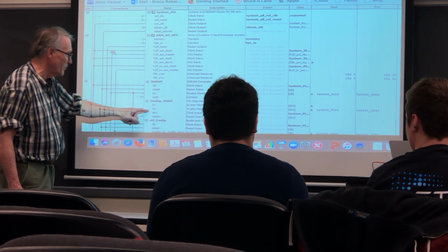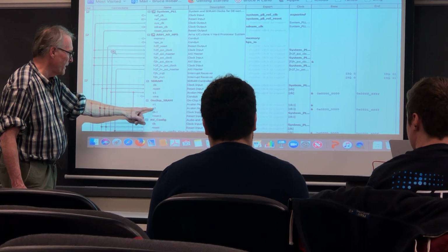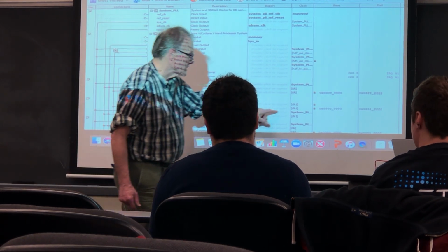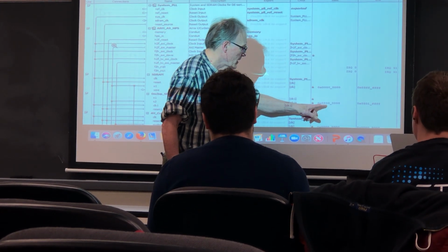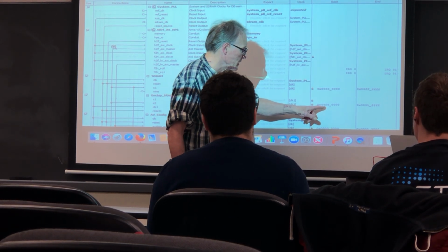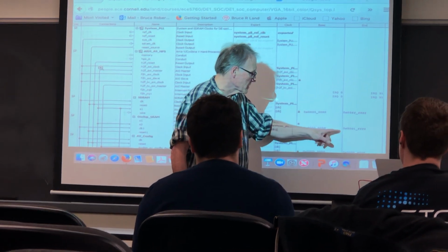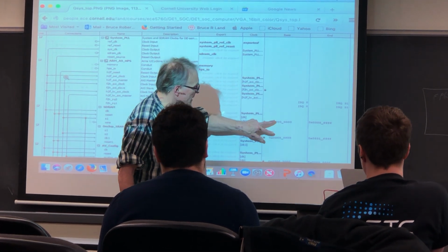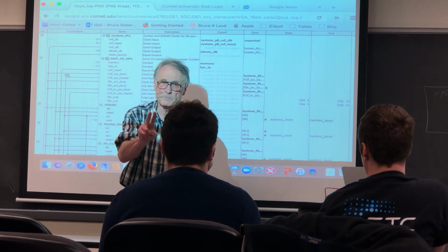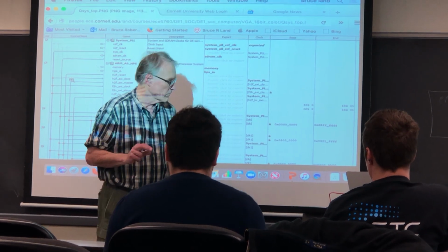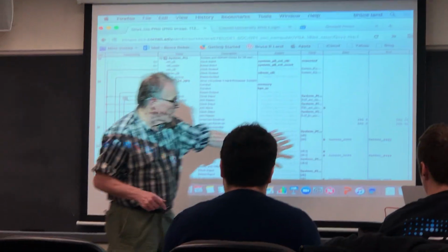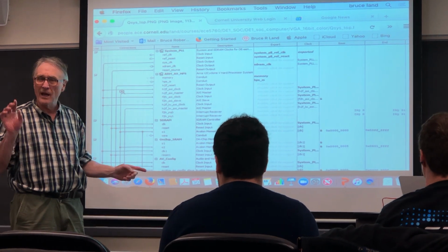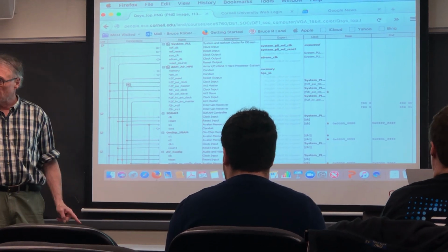The slave 2 is on the Qsys master, and it has an address of hex 800 0000 through 801 FFFF. So these two cannot overlap, because they are on the same master. On a master, every address has to be unique.